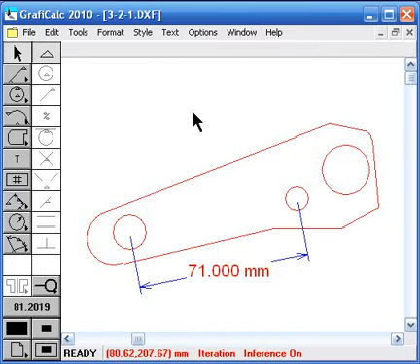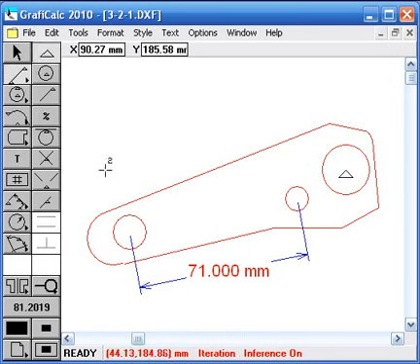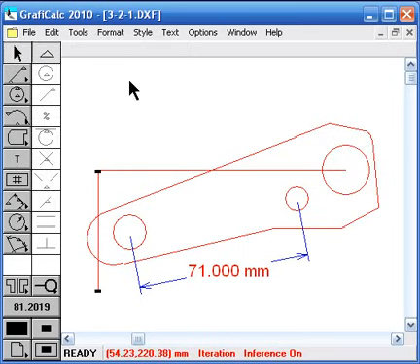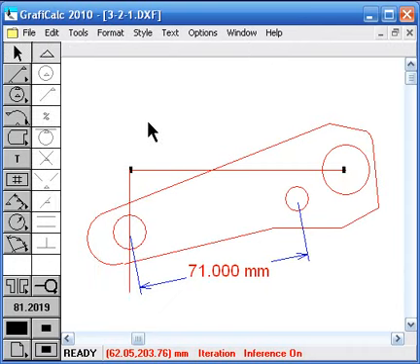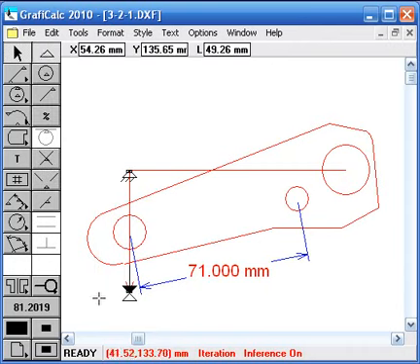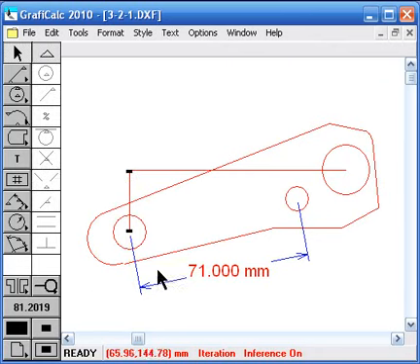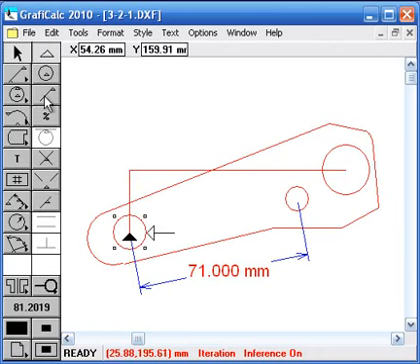So now he says, okay, I'm going to hold this to 0, but my machine will have a tolerance in the X and Y direction. So he defines the tolerance vectors to simulate the process. So the nominal value of this length is 90 millimeters. He's constraining the tolerance chain. And the nominal value of this is 25 millimeters, and this is located at the end of this line.